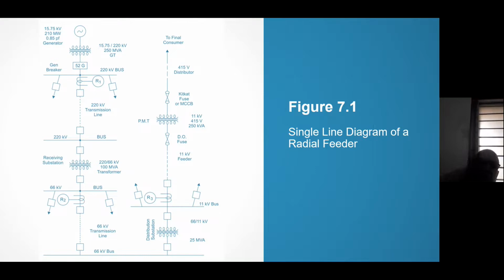If you see the pole mounted transformer now, probably, I don't know, because the porcelain tubes are out of stock, they use simple stone available in the streets, so that by the weight of the stone the wire will come down when it melts. So the dropout fuse is for protection of internal faults in the distribution transformer.